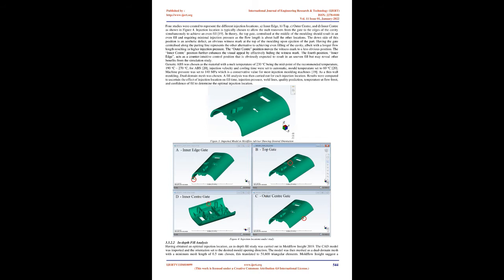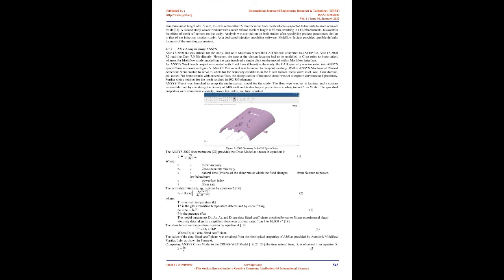Regression analysis was carried out to construct a quadratic model for prediction of cycle time within an accuracy of 96.88%. Results obtained from the RSM analysis were evaluated through analysis of variance, ANOVA, 15 table to determine an optimal cycle time that reduces or eliminates the shrinkage and warpage, based on varying the four selected process parameters 16.